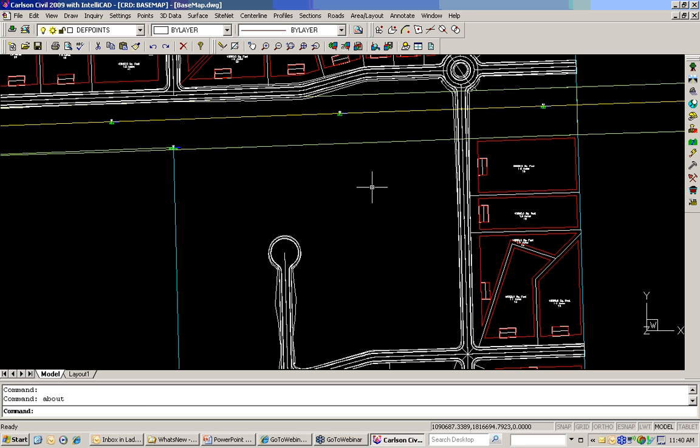And I'm just going to make a few quick layers, so just run these at the command prompt. I'm going to make a layer, and we'll make a layer called 1. We'll make another layer called 2, and I could probably just separate these with commas. And I'll just make another one, I'll call it 3. And I'll just put in a maybe rectangular building pad. And we'll just put it in like this, right about in here.